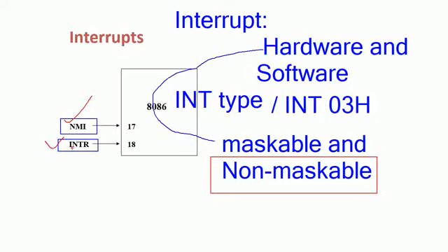And we are having the INTR now, a maskable interrupt. That may be any kind of interrupt. Let us suppose I connected the pen drive. If the microprocessor is doing important work, then the pen drive is generating one request to the microprocessor saying that I just connected to you. So the microprocessor may or may not work on its functionality immediately, depending on its present status.